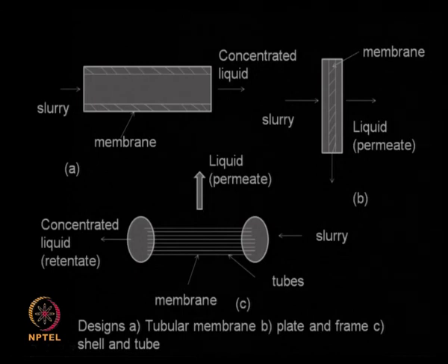So this is another design. If you want to replace a tube, you need to open up this heat exchanger pipe, take one of these tubes which might have been fouled beyond use or might have been physically mechanically damaged, then you can put another tube here and carry out your job. So that is another way of looking at this type of shell and tube design actually.